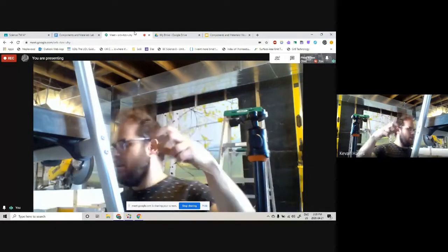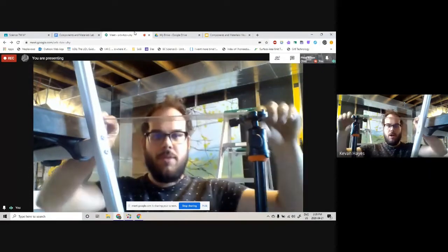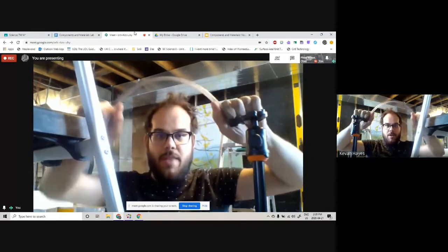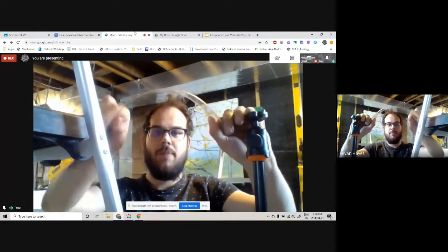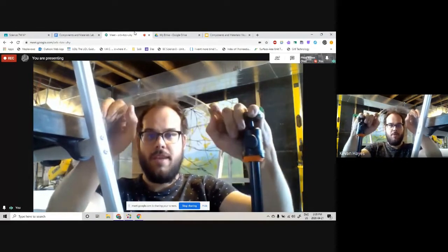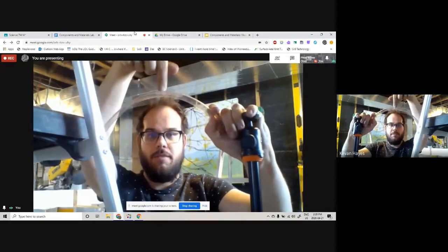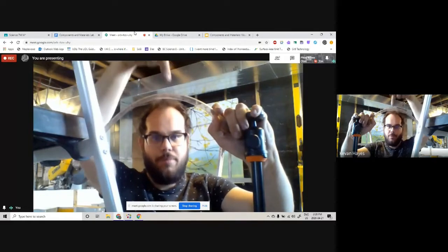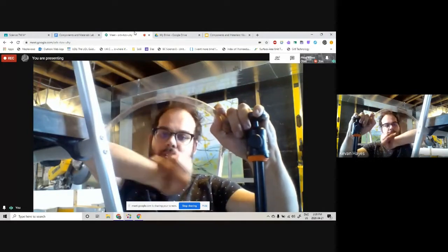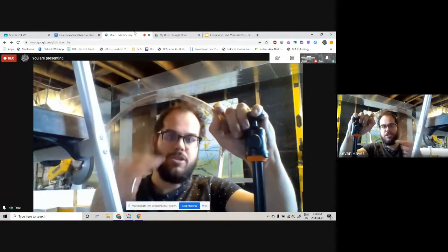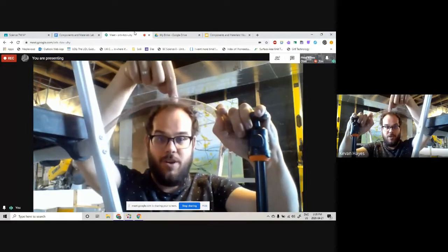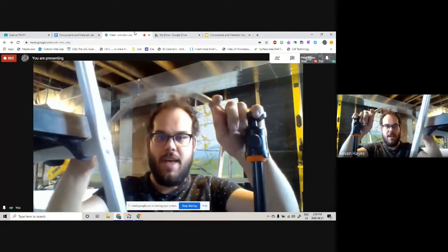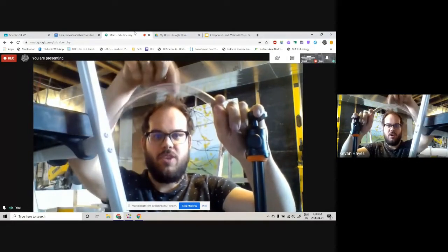The idea about an arch is when you form an arch, you form it by taking the two ends and pushing them together. And that causes the top to move up. So now when this thing is actually experiencing force on the top, it's trying to undo what you've done, right? It's trying to push this flat again. And as a result, the two ends are going to push out. So if I push down on this, it tries to push the two ends away from each other. And so as long as those two ends are well supported, then this arch is very strong.